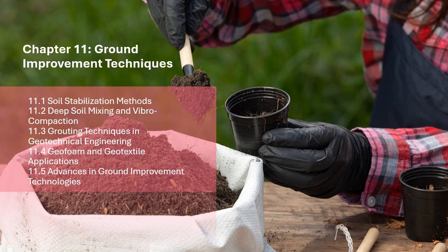11.4.1 Geofoam. Properties and applications. Geofoam is a lightweight, rigid foam material made from expanded polystyrene, EPS, or other similar materials. Due to its low density and high compressive strength, geofoam is used to address challenges associated with heavy soils, subsidence, and weak ground conditions.